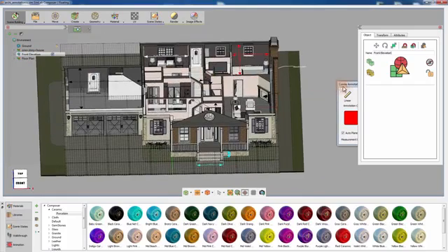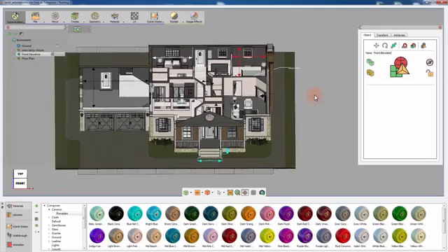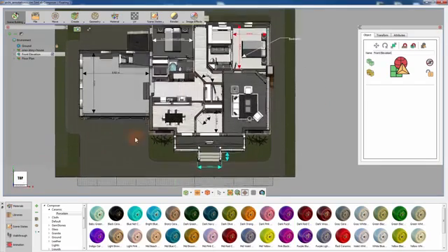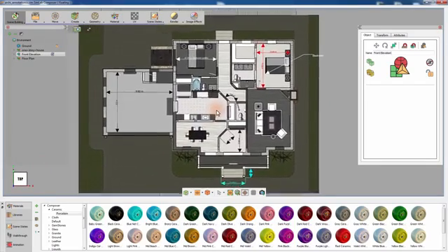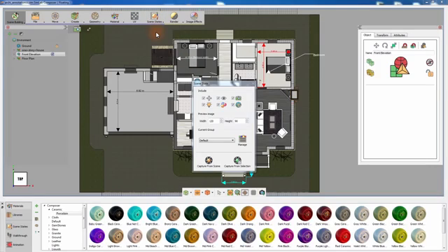Hide the front elevation group and the roof objects, then set the camera to a top parallel view. Then go to the Scene States menu and select Capture. Scene States allow you to capture several attributes from the scene and store them. When the captured scene states are activated, it will reapply all the attributes it stored back into the scene.